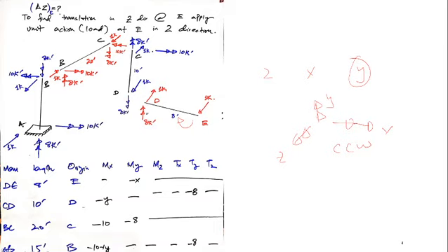Okay, again I have to balance this joint. This is counterclockwise, this is clockwise. Okay, one kip equal and opposite one kip. Again, this 8 kip foot would be balanced with 8 kip foot because it's a pure torsion. It would be transferred as it is. This one kip with one kip. Again, this one kip is in Z direction, and this member is in Y direction. So there would be a moment in X direction. Okay, this one kip is forming a moment that is clockwise. 1 into 10. Resistive would be counterclockwise, minus 10.